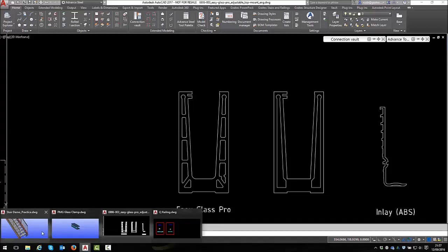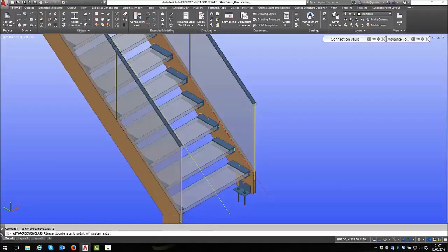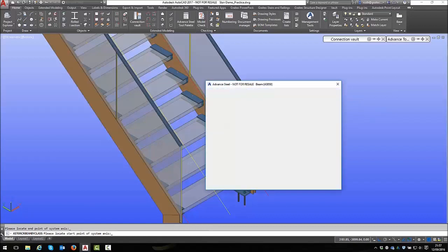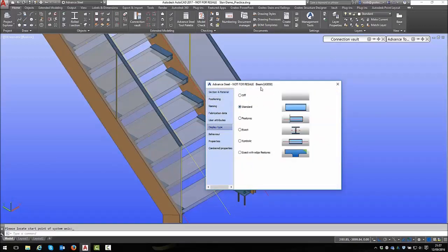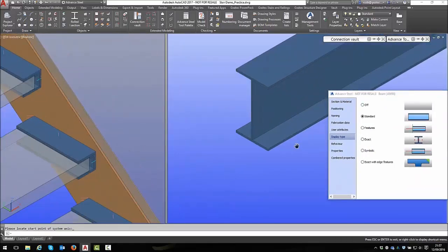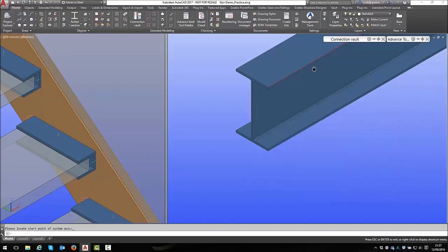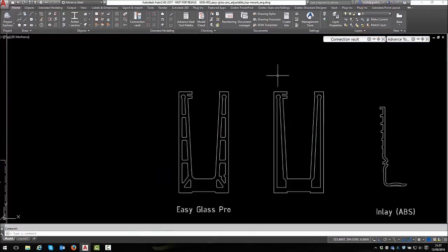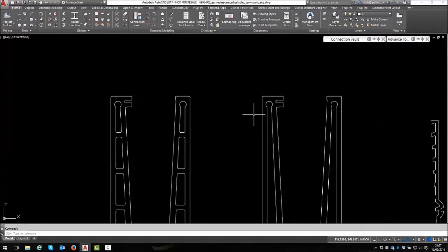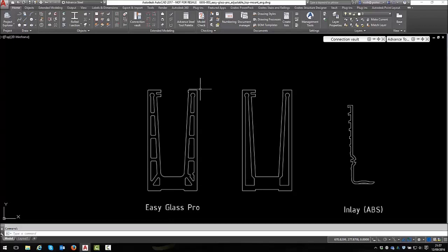You know that when we're in Advanced Steel and we draw a beam, we have the standard display type here, and if I zoom in and select exact with edges, you'll see I've got all the radii on the beam. That's exactly the same with my user section. If I go to my user section here, this will be the standard display. In fact, I didn't even need these bits in here. I could have deleted those as well. And this is the exact with edges.